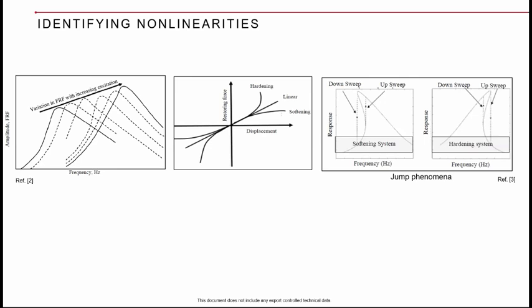Similarly, you take actuators with clearance joints. I mean, the piston head will have clearance with the cylinder, right? So at these joints the clearance should close, and during that process you will have stiffness being built with the excitation levels that will result in a certain nonlinear stiffness relation.